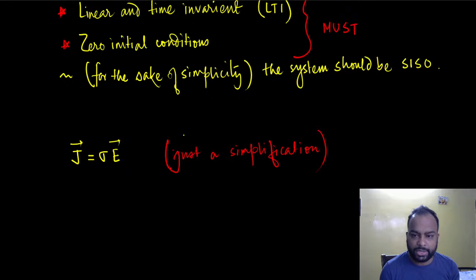So what we instead do is assume that the system, or the devices or equipment or elements that we are using, are linear about the operating point. So if I have a resistor that is carrying 1 ampere current, I would assume that at 1 ampere, and in whatever frequency range I'm applying, the element behaves linearly. We assume things like that. So linearity is nothing but an assumption in real life.